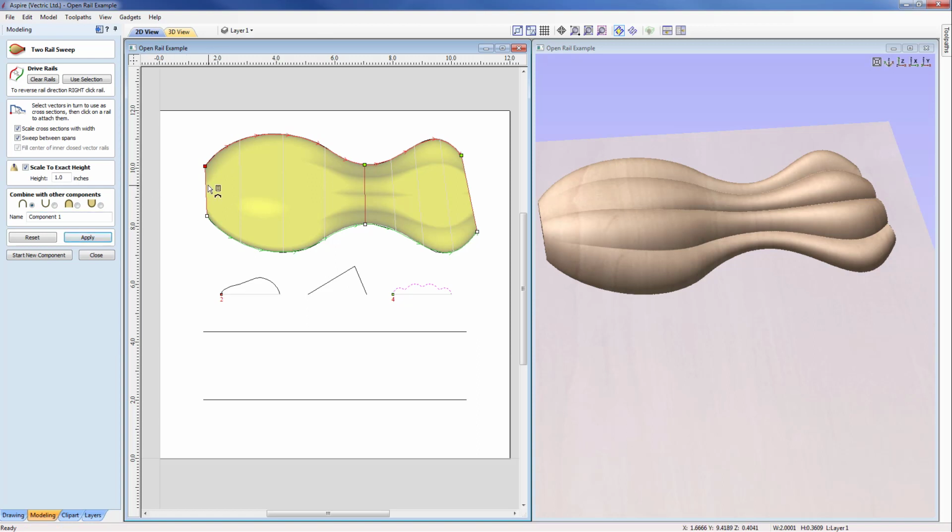So we're getting the morphing really from the front curved shape to this shape by this region in the middle, and then continuing that region all the way to the end. Now if for instance I didn't want that and I just wanted it graduated from the curved shape here to this humped version at the far right hand side, then I would just right mouse key over that cross section and say delete cross section, and then I would need to reapply, and now I could see a better sort of a slower transition from the left hand edge to the right hand edge.